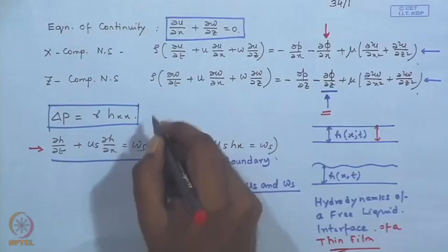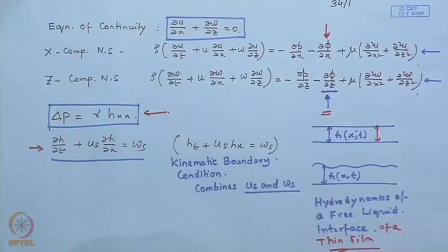We assume that the undulations at the surface are axis symmetric. Then we invoked the condition for the long wave instability, which implies that del h del x is very small, close to 0. Once you plug that into the Young Laplace equation for an axis symmetric surface, this is the form you are left with.